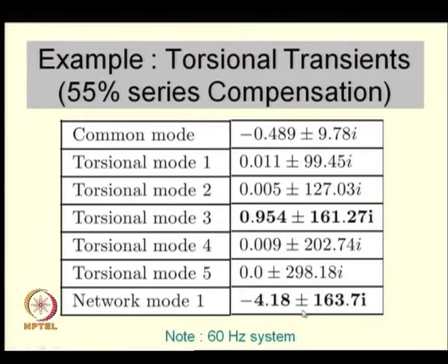This of course, the equations are formulated in the DQ reference frame, remember. The subsynchronous frequency reduces if the equations are formulated in the DQ frame, if XC, that is the reactance corresponding to the series compensation, increases. So, one may actually have to limit the amount of series compensation, so that there is no torsional mode and network mode coincidence. In fact, this tells you an important thing, that stability issues in certain conditions can restrict what you can do with the system.